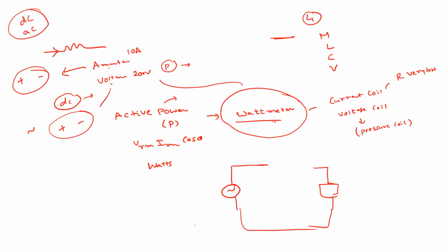Because it is connected in series with the circuit. An ammeter will connect in series and a voltmeter will connect in parallel, right? So that is the basic. Agree? Yes, sir. Okay. If you connect a large resistor in series, what will happen? There will be some voltage drop. So that's why an ammeter has low resistance and a voltmeter has high resistance.